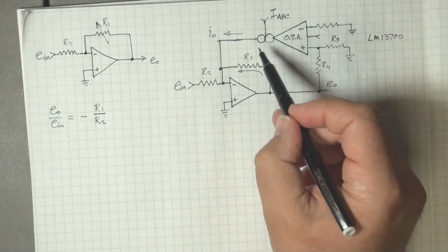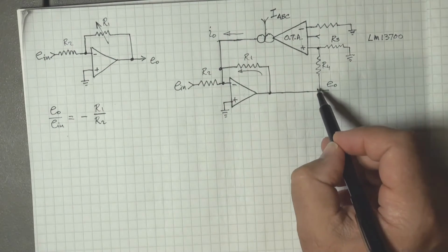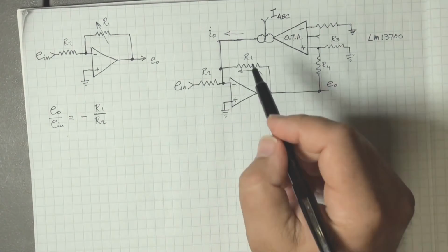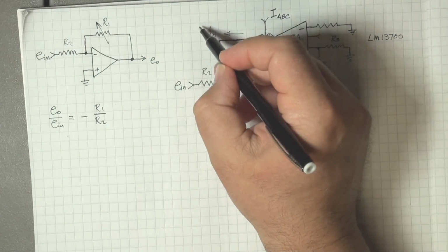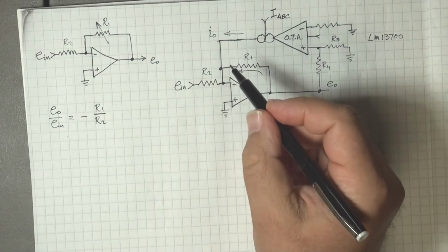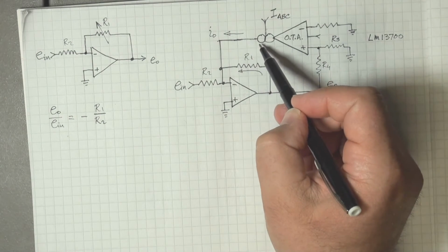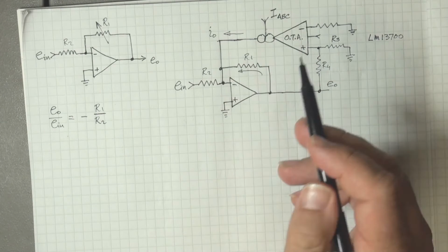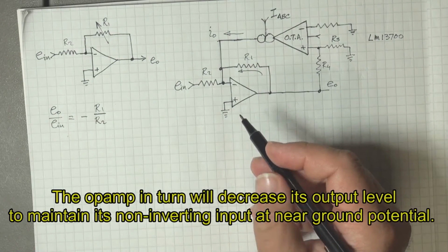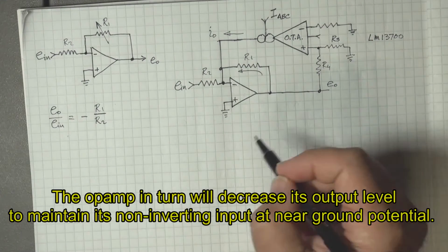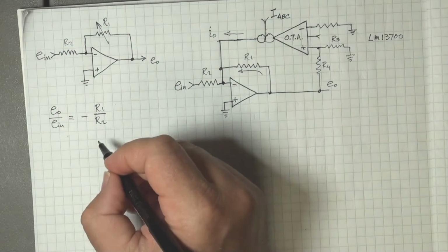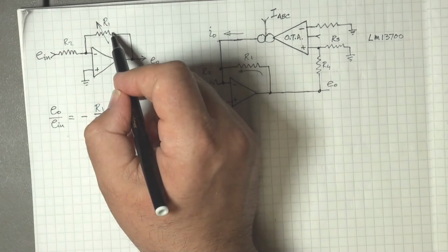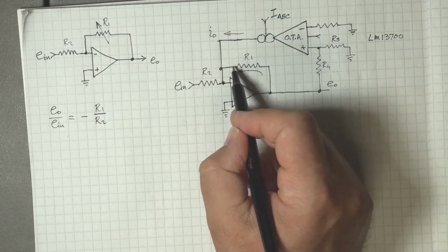Of course, the output current is directly proportional to the output voltage appearing at the output of the op amp. So it's a signal current. In other words, it's not static. What's happening is the current feeding into this junction of the op amp is increasing. That, in effect, is very similar to changing the value of the overall feedback resistor in this branch of the circuit.